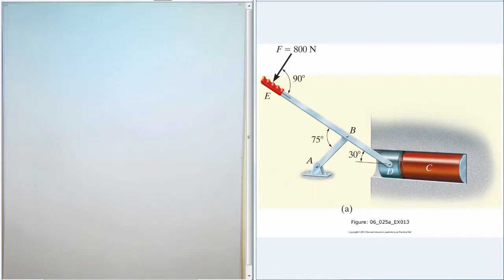The steps are to first draw the free body diagram for each part and then identify all the two-force members, and be sure to show that the forces which are common to two parts are equal and opposite. So that is, a force acts in one direction on one part, and then on the adjacent part, the force acts in the other direction.